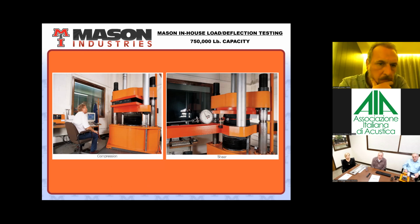We have our own in-house testing facility, and we're testing, in this case, bearings in compression and bearings in shear, all with the idea that every bearing that goes under a building or is utilized structurally to isolate noise and vibration is going to be tested to 2.25 times the rated capacity.